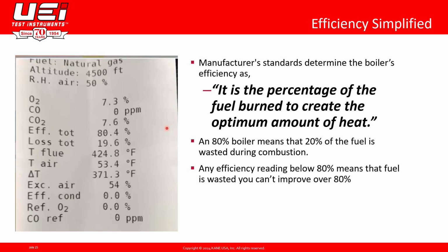So it is possible that your combustion efficiency is not the same as the AFUE, because the AFUE is your annual fuel usage efficiency. And that's done over a very long period of time in very nice conditions. And we know that we are working in the real world. So if your AFUE and your combustion efficiency don't exactly match, that's okay.